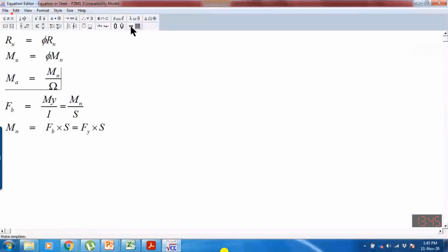In equation number one, if I am comparing the allowable applied service moment with the capacity, then equation number one will become Ma equal to Fy into S divided by this omega.